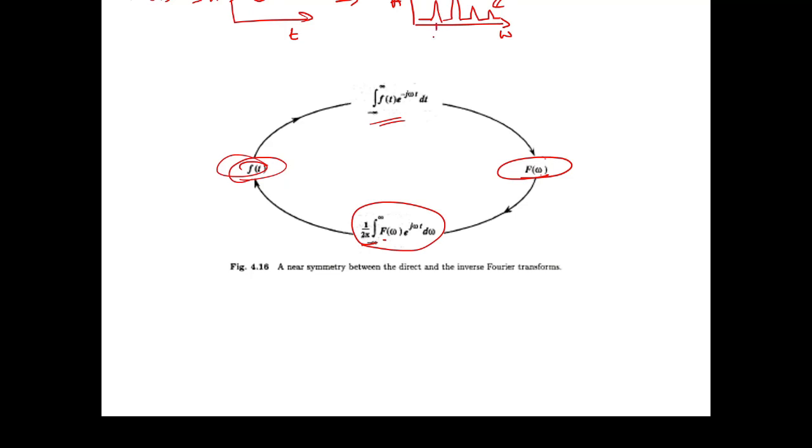Say, for example, at 50 hertz, at 100 hertz, I'm just giving you an example, 150, say 200. Now say you got this signal and you can see that you have a 50 hertz component, so you might be having some corrugation over here. You don't know whether these corrugations, which are basically the noises, are 50 hertz noise or not. So how do you ascertain what type of noise is there?